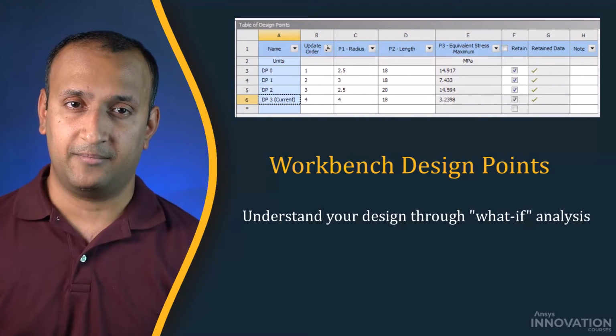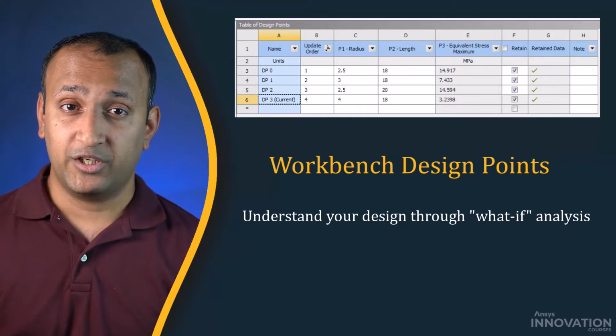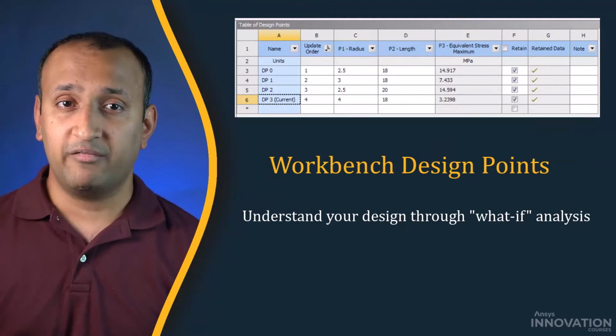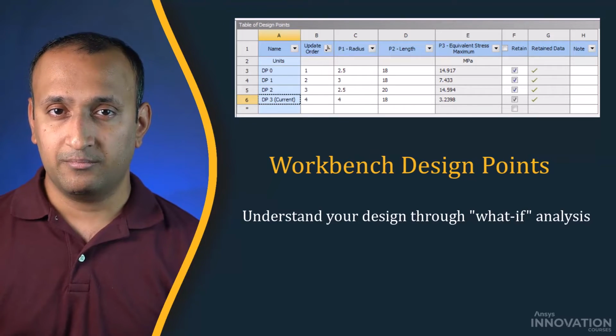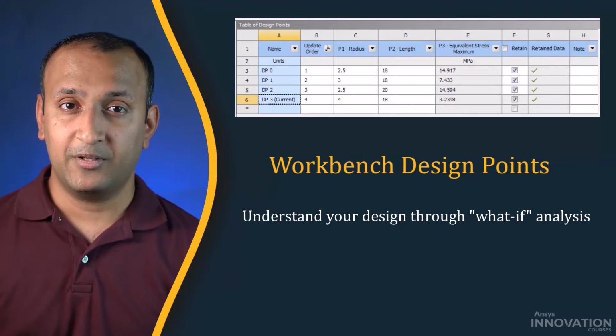What-if analysis using the table of design points is a first step in our effort to understand our design. It's worth noting that automated optimization tools such as DesignXplorer or optiSLang are also available, but are outside the scope of this lesson. Now, let's see how to set up, solve, and post-process a parametric model in our walkthrough example in Ansys Mechanical.